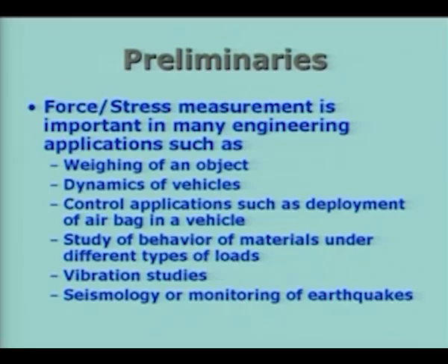And sometimes we also have vibration because of time varying sources, time varying forcing, and these vibration studies involve the study of vibration forces a particular system is subjected to, and also the amplitude of this vibration which the system responds to. So, we would like to measure the vibration in terms of its frequency, in terms of the forces it induces, and also the accelerations because of that.